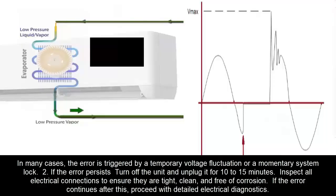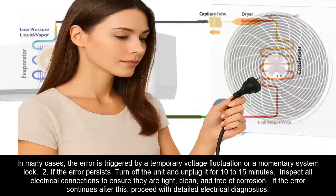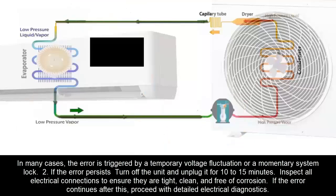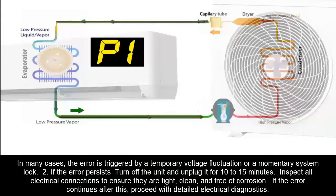2. If the error persists, turn off the unit and unplug it for 10 to 15 minutes. Inspect all electrical connections to ensure they are tight, clean, and free of corrosion. If the error continues after this, proceed with detailed electrical diagnostics.